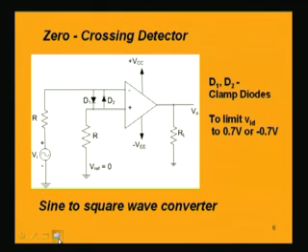That type of voltage, if we want, then we have to consider a circuit where we will be getting this type of voltages, and that will be possible if the reference voltage is made 0. So, let us take one example of that type of zero crossing detector. This circuit which we are going to discuss will be able to detect when the input voltage crosses 0 and in what direction.